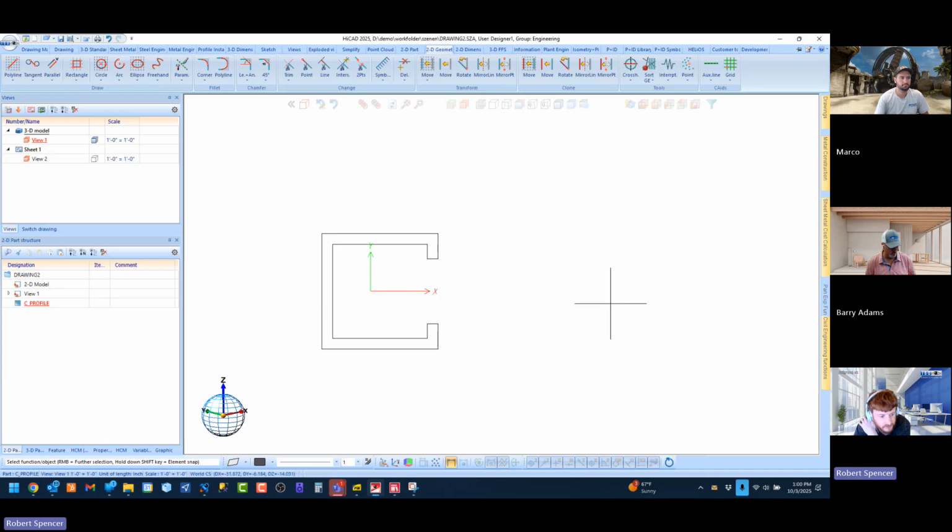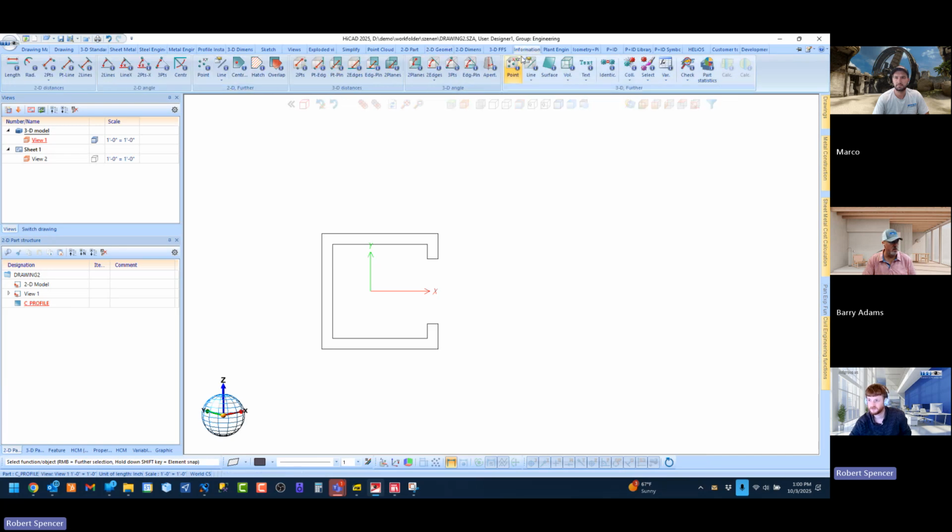First off, do you guys have enclosed polylines, or did you have a problem like I did? Mine are not wanting to close, I don't think. How did you find that out? You can analyze it with information and polyline.